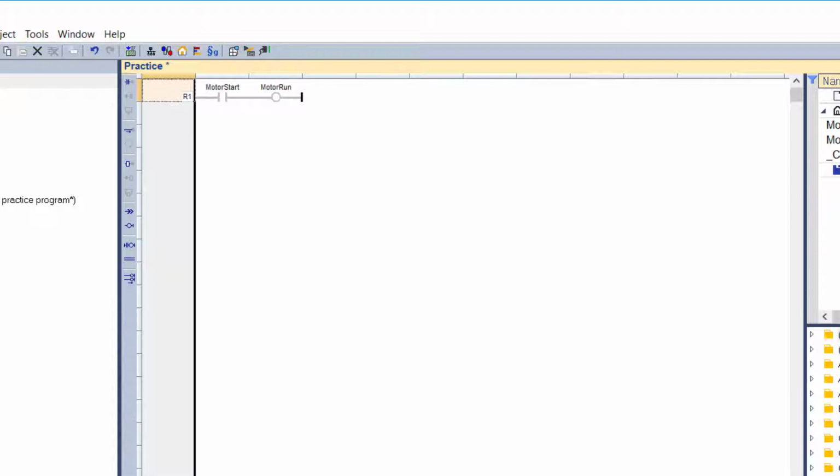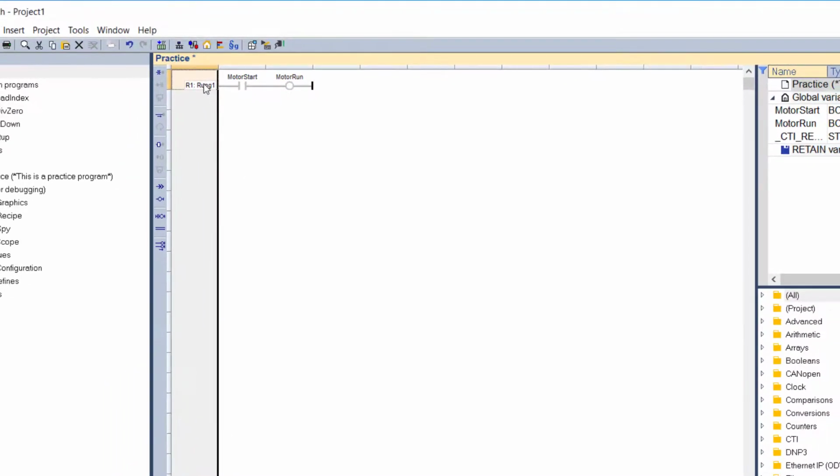A ladder diagram is a sequential list of rungs. Each rung represents left-to-right Boolean power flow, that begins with a power rail, and finishes with a coil or a jump symbol. Each rung is identified by a default numbered label, displayed on the left of the power rail. The rung label can be used as a target for jump instructions. You can edit the rung label by double-clicking in the rung head, on the left margin. The ladder editor enables you to manipulate whole rungs, by selecting only their head, in the left margin. Once selected, you can use normal cut, copy, and paste operations.